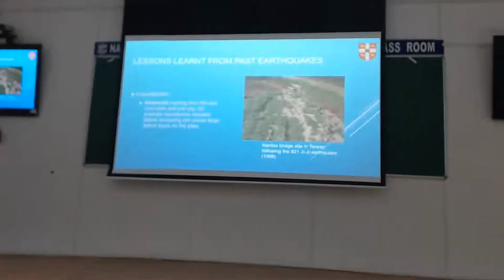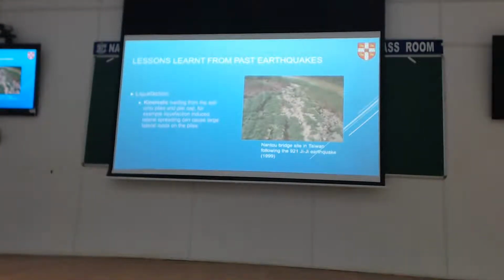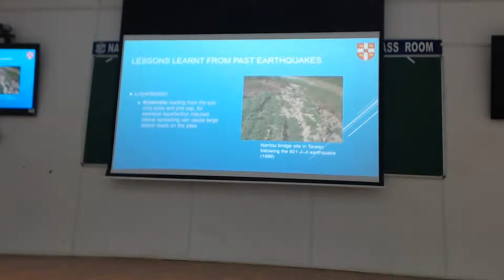The other issue, which I alluded to yesterday, is this issue of lateral sway. Where you've got ground, and you can see the river, of course, the bridges are always there because you want to cross the river. So the river is going to be there. And because a river carries water, the water table is always going to be shallow.